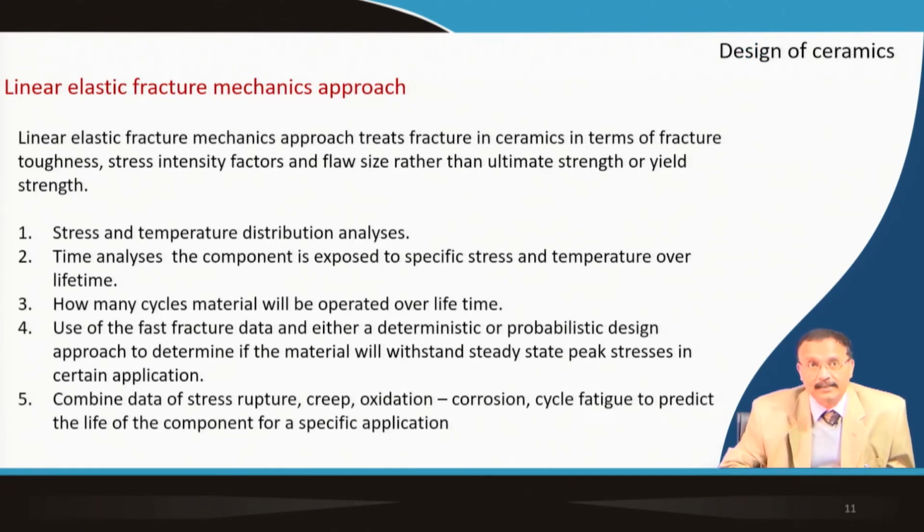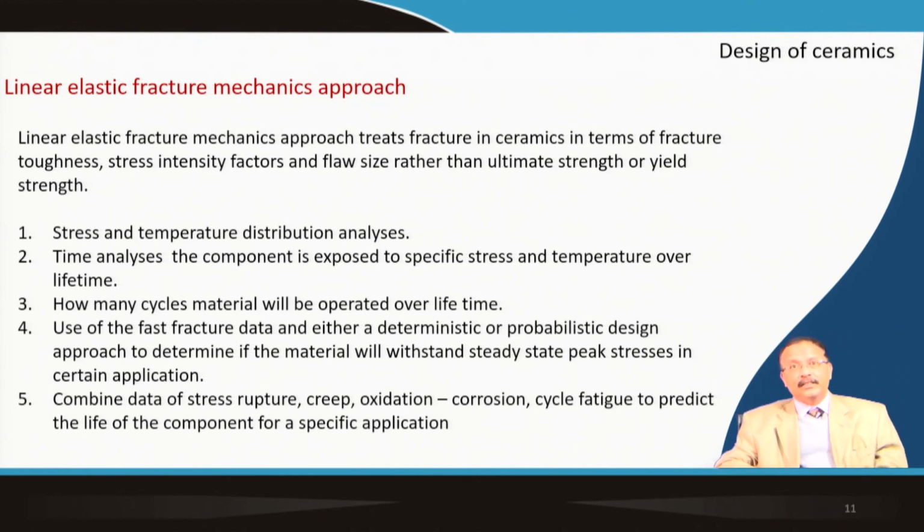The final thing is related to mechanical engineering, and this is the linear elastic fracture mechanics approach. Linear elastic fracture mechanics treats fracture in ceramics in terms of fracture toughness, the stress intensity factor, and the flaw size, rather than the ultimate strength which we were talking about so far. Several analyses are done, and it is computational work that is usually needed to have a much better idea than the 2 parameter Weibull distribution.